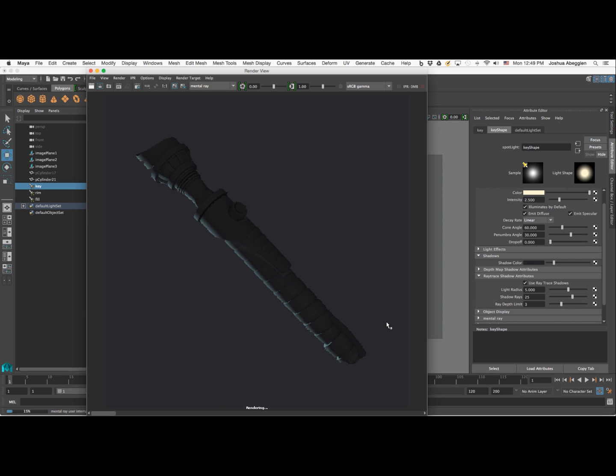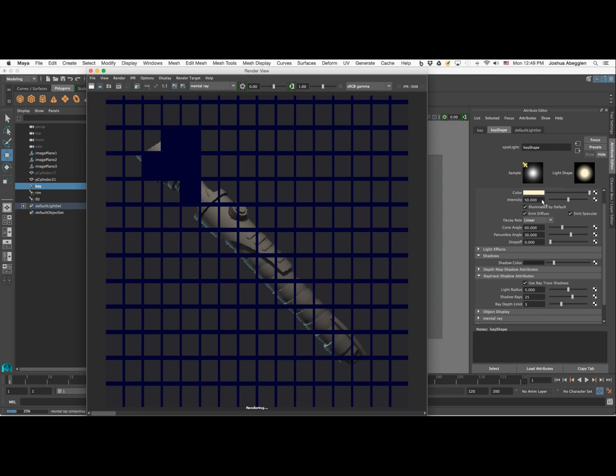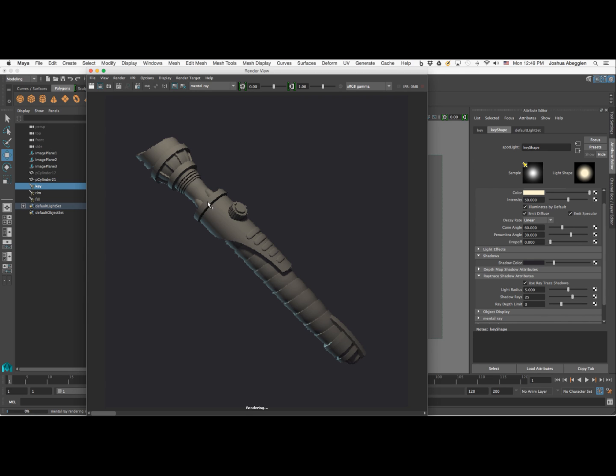So I'm going to go ahead and press Escape and abort this render and play around with our intensity until we get it set to a good number for this particular application. I'm going to really jump the gun and go from an intensity of 2.5 to an intensity of 50 and start another render right here. Now the cool thing about this is the closer the object is to the light source, the more heavily featured the halftone and the specular highlight would be, and the farther we get away from it, it's going to gradate from lighter values into darker values, doing a better job of simulating how lighting would occur in real life.